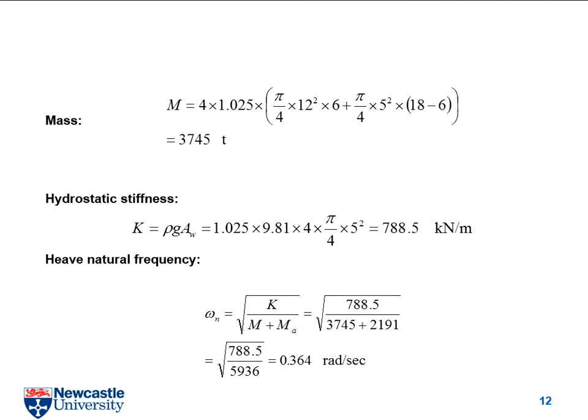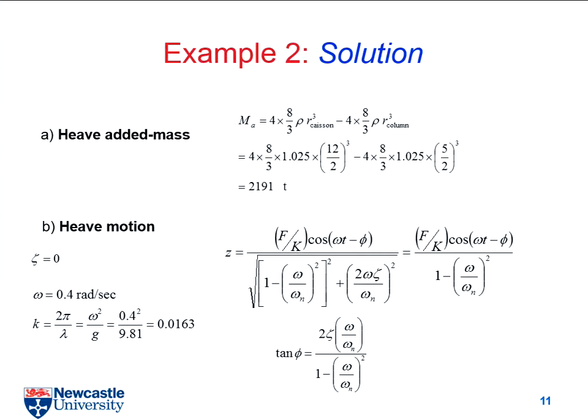And by the formula form, we also know how to get the added mass, because in the last page, is that last page? Oh, page 4. We have 2 estimations for added mass. The first one is for heel motion. The second one is for horizontal motion. Okay, so this one is for heel motion, and you can use the first expression in that form to estimate what is your added mass. And because you have your geometrical features of the structure, we will know the real mass. So add them together, it will be the mass you need for your calculation. Okay.